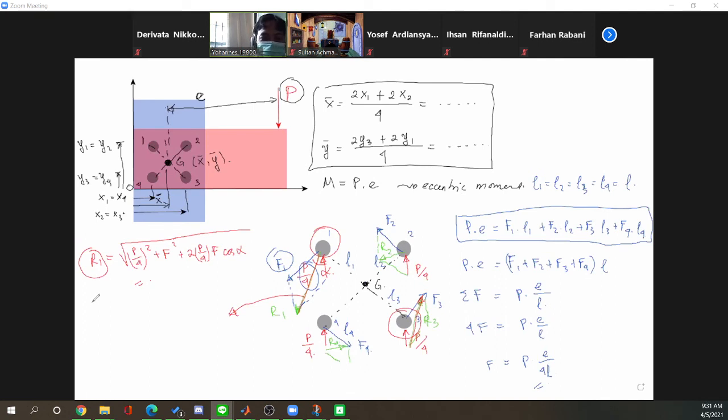Okay. So because this rivet has only single shear area, then the shearing load is R1 over the shearing area of the rivet. Okay, so this is R1 divided by pi over 4 times the diameter of the rivet squared.